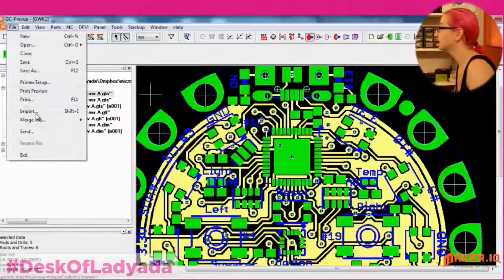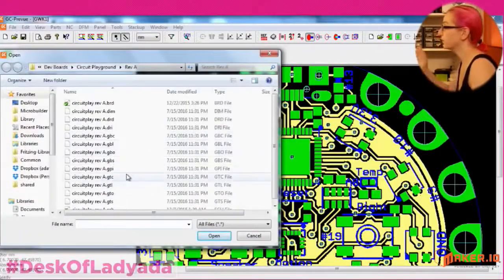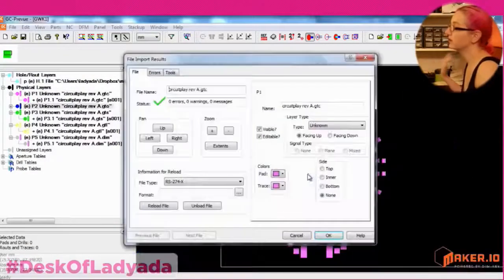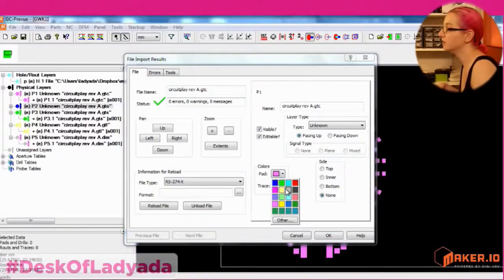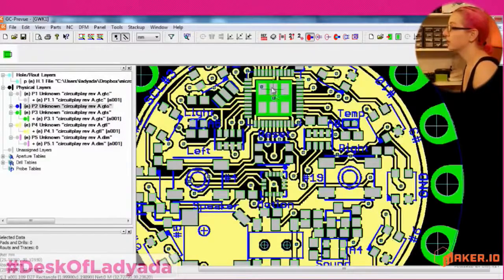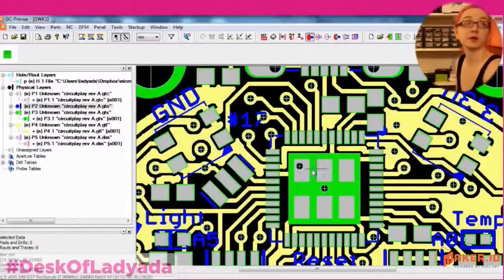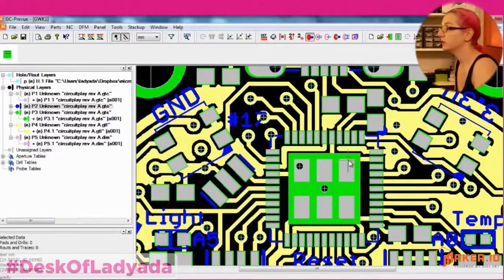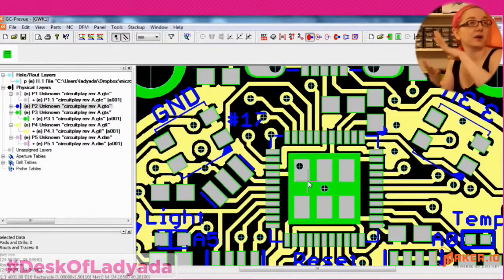And then finally, the cream layer, that's where the solder paste will come in. Not important for the prototyping, but if you have a mistake here, it will bite you later. It's harder to fix later. So make sure you check where the solder paste will go. For example, on ground pads, you don't want full coverage because the paste would make the component float. So instead, you put like 6 little dollops. Otherwise, it's too much paste.